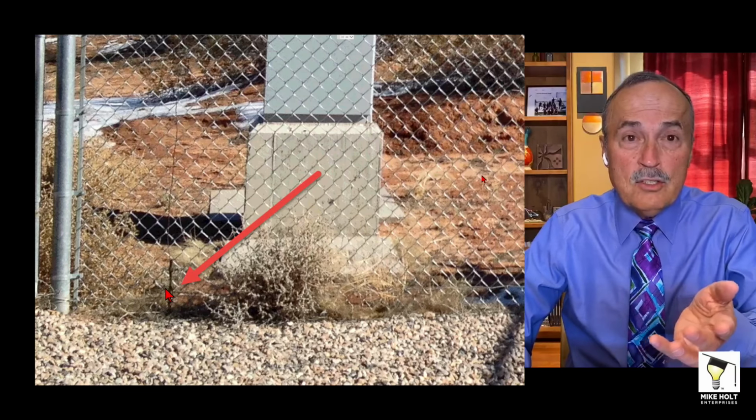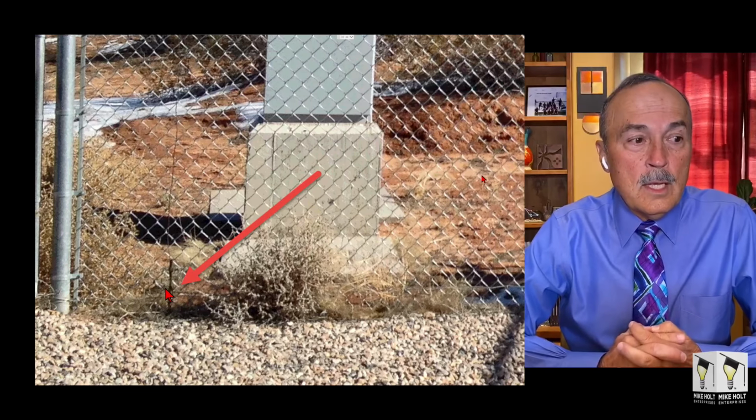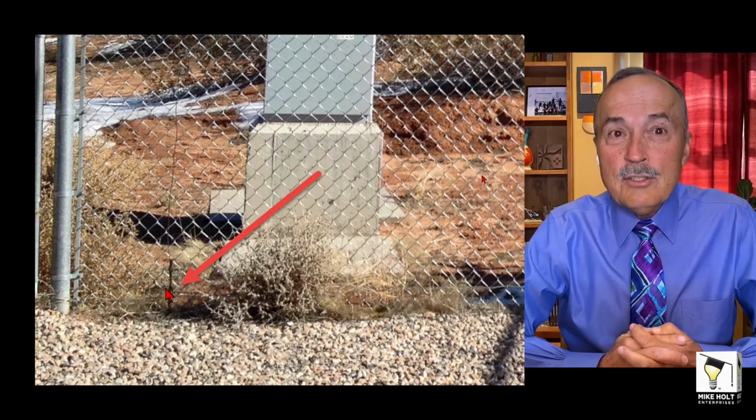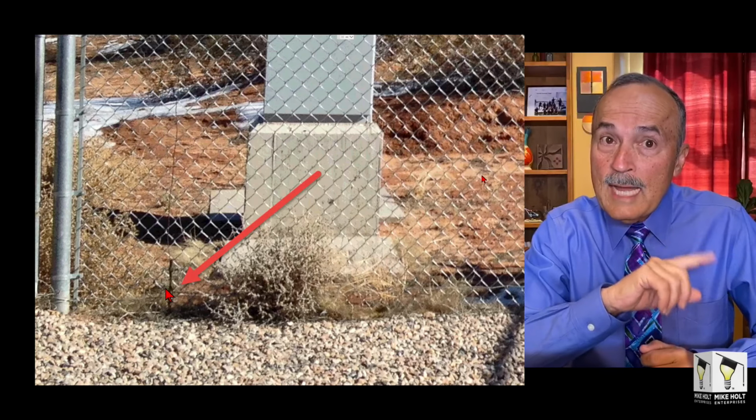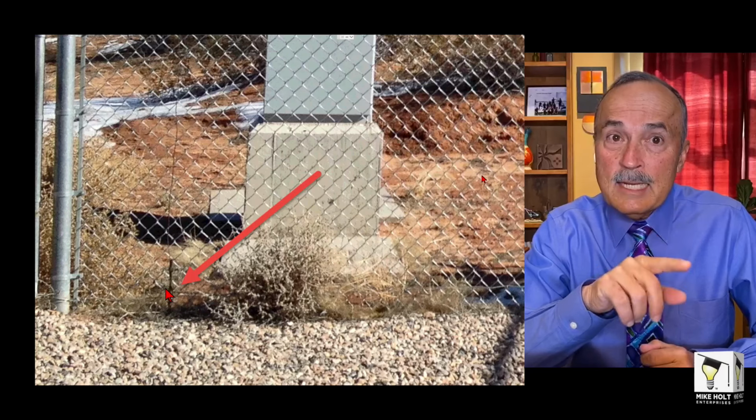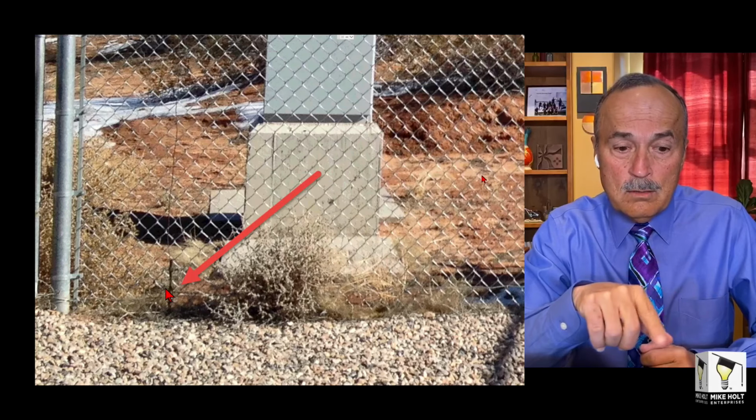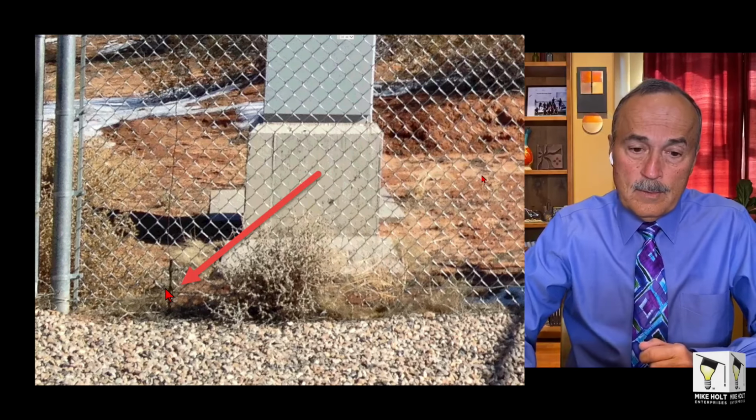If the fence became energized, it's likely to become energized, we talked about that before, right? The term likely to become energized, that it has to be connected to an equipment grounding conductor. Well, a ground rod is not going to do that.